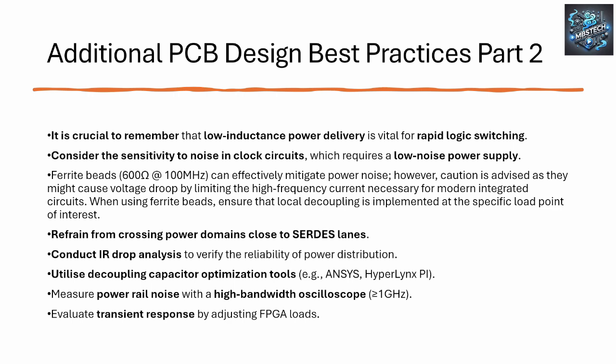Measure the power rail noise with high bandwidth probes, clip springs. Don't use the little 6-inch earth probes, they're no good. Pull them off your scope probes. Make very, very close measurements with the tip of the probe and a ground coupled measurement. You can get special pins for your scope probes. Use high scope probe bandwidths, low impedance, low capacitance. Make sure you can actually read the frequency of interest that you're trying to read.